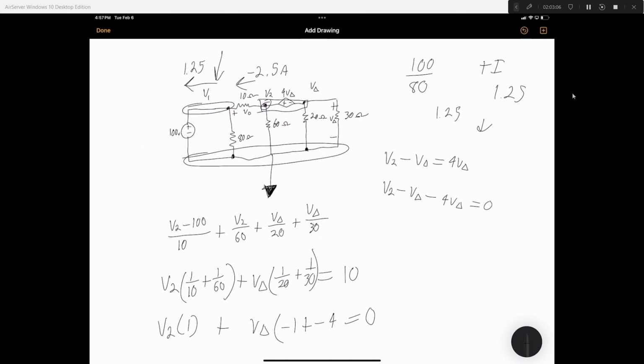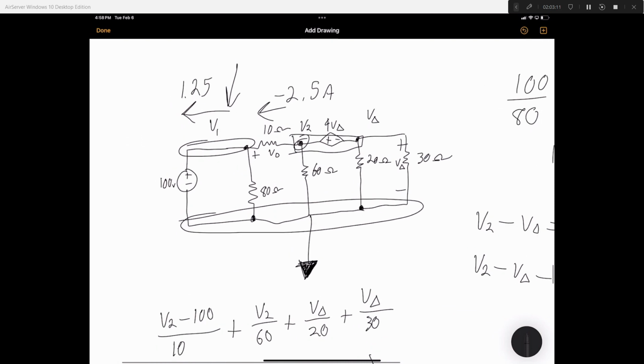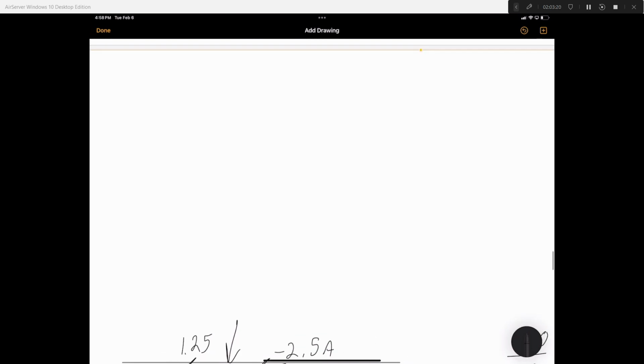All right, I got the answer, just by some sheer thinking. So the voltage source is here, right? Let's draw what we have so far. We have a node, and we know the current coming down is equal to what? That's 100 divided by 80, 1.25. We know the current going this way is negative 2.5, and you want to know the current that's going this way.